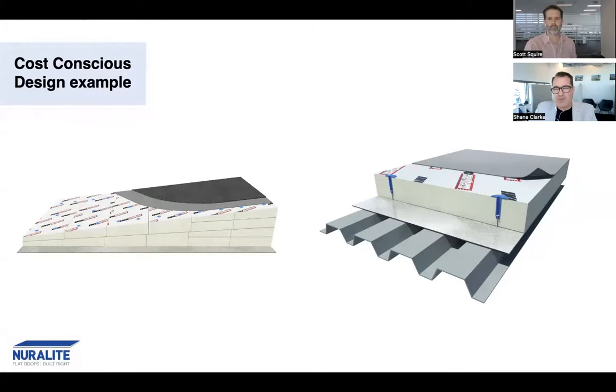And because this was a pretty basic rectangular shaped roof with very little detailing, a large flat 1,500 square meter area, the single ply TPO option proved to be more economical, as there's less laps. It comes in a 3.6 meter wide sheet, and the installation costs come right down. So that was a real life example of a project we've recently been involved with, where we looked at some cost conscious options, but still kept the durable waterproofing finish, which you probably want out of your roof, along with the performance of the insulation.